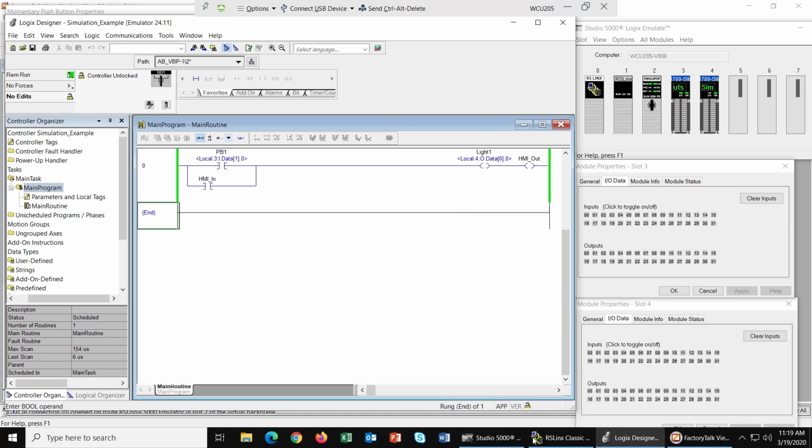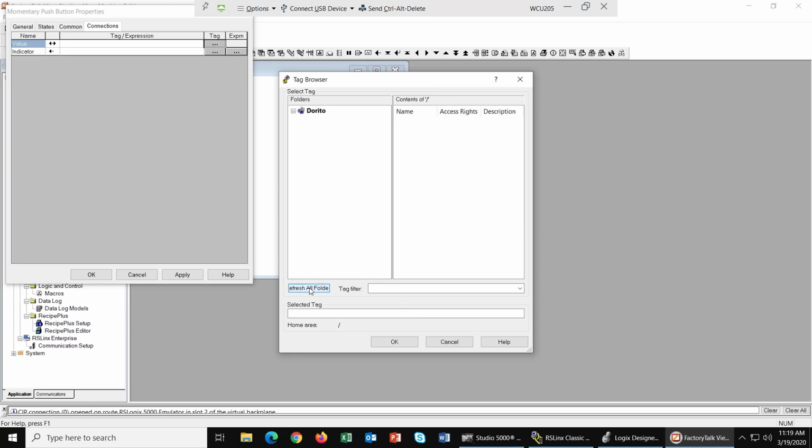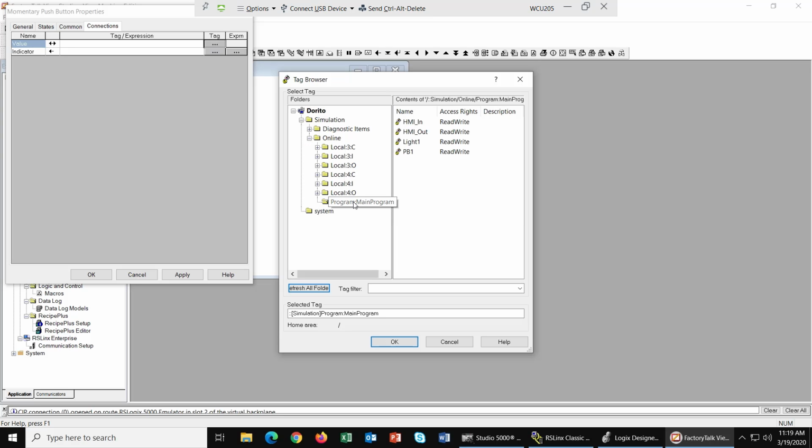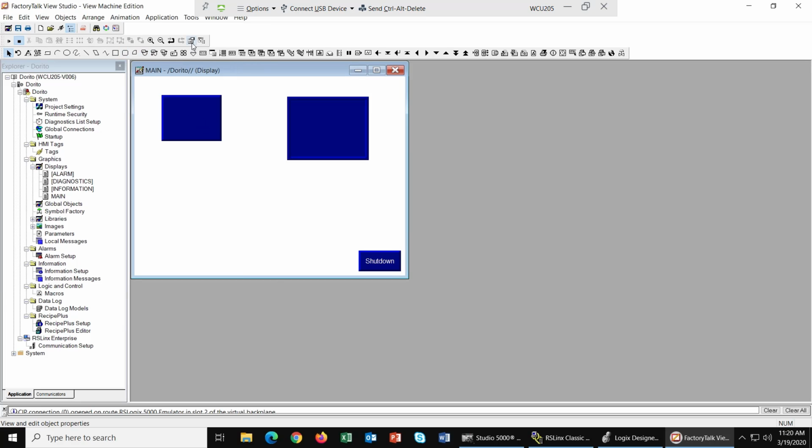So I am online. Okay, let's go back to Factory Talk, and I'm going to tag this out, and let's see if it'll refresh all tags here. Come on, baby. And there's my system, there's my simulation, there's my online, there's my program, and what we're going to call this is HMI input. Okay, so there you go. So that's going to be the HMI input, and we're going to apply that. So it looks like it's found that. At this point, I should be able to go ahead and click my simulate button right there.